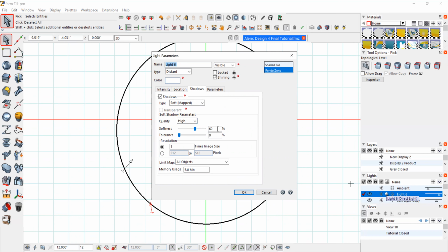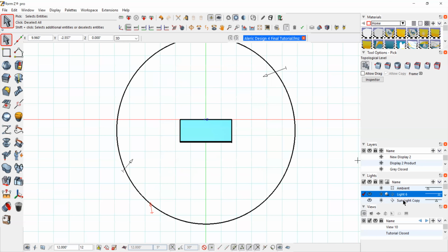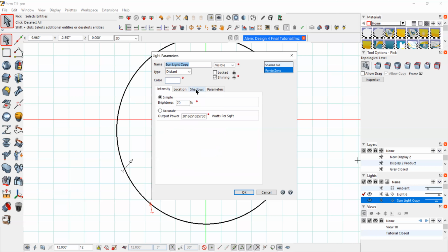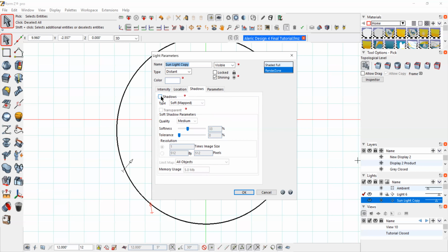If you do hard shadows, you get very hard ray traced shadows, which can be fine. It's like a certain kind of effect. But in general, I'll just use that. So that's all, every light has that. So these other two lights, I usually back off on them. The intensity would probably be 70, a bit less. And shadows, I just have them turned off.